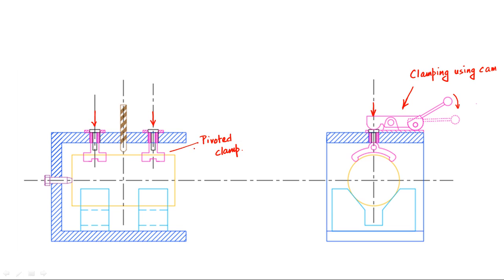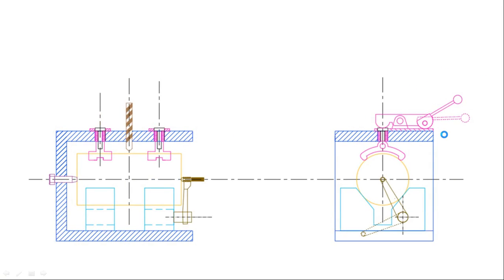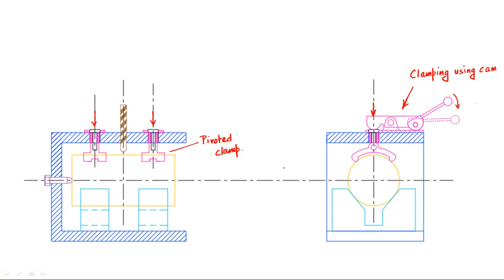Now after completion of the clamping system, the next step that will be needed is machining. Before machining, we will use a pusher type device that can apply an axial force in this direction, so that we can ensure more that the product will not move during the operation. So one pusher we can use along this axis.